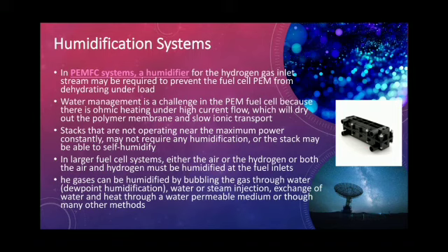Stacks that are not operating near the maximum power constantly may not require humidification, or the stack may be able to self-humidify, but if the stack is constantly operating near maximum power, it will be drier and humidification is needed. In larger fuel cell systems, either the air or the hydrogen or both must be humidified at the fuel inlets. The gases can be humidified by bubbling the gas through water or steam injection, exchange of water and heat through a water permeable medium, or through many other methods that are currently available.